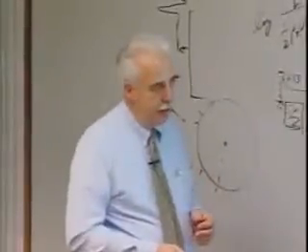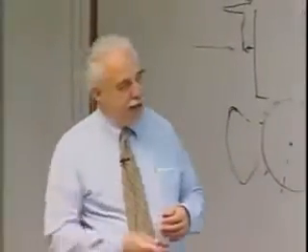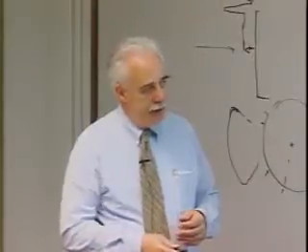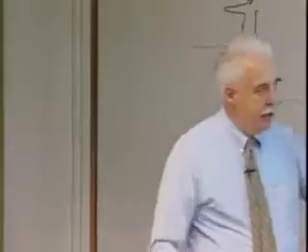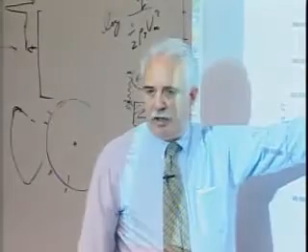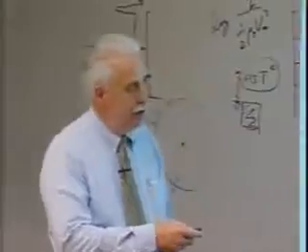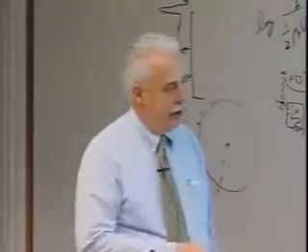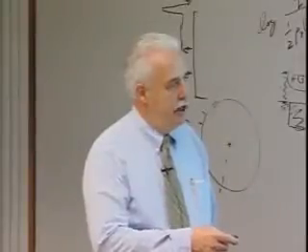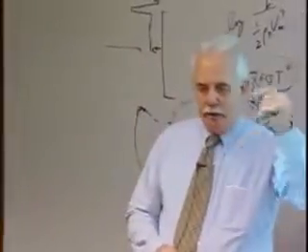You've seen the ablator from Apollo, and you've seen a tile that's really had some severe environment from the shuttle. But basically, here we had a simple configuration. Here we had a much more complex configuration. We had capability to fly it, and we had capability to avoid excessive heating. It takes about 20 minutes to enter, 10 minutes along this heating boundary where basically your heating rate comes up and you are on a plateau. And you'll see that in just a minute.